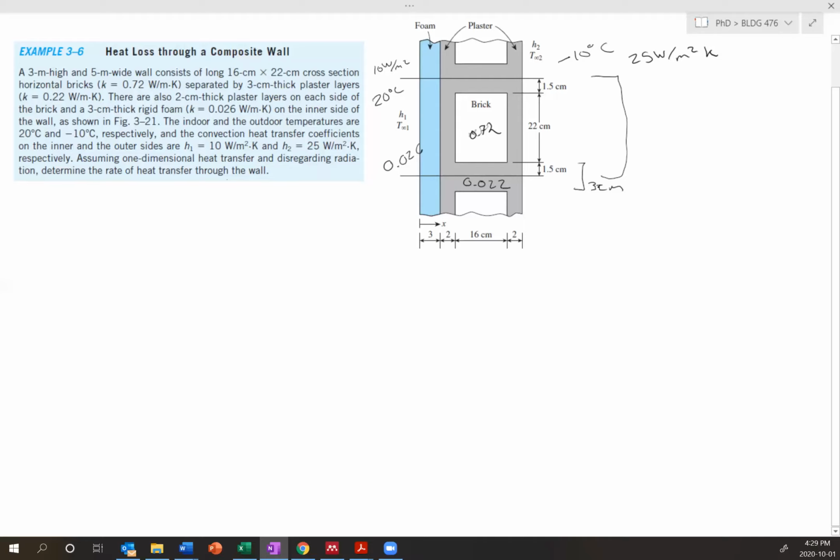And I'm sure you've seen it before where you're given an equivalent heat transfer of a wall. And whenever they do that, it involves a lot of this kind of analysis where you consider all the modes of heat transfer. So there's heat transfer coming through this middle part. You can see that this is slightly lower than the brick, so the amount of heat that can escape through there is slightly less than the brick.